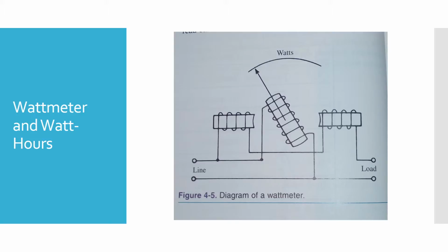4.3. The wattmeter and watt hours. Power in an electric circuit is equal to the product of the voltage and the current. To devise a meter that measures watts, a movement similar to the D'Arsonval movement can be used. The permanent magnetic field found in the D'Arsonval movement, however, is replaced with coils from an electromagnet. This type of meter is referred to as an electrodynamometer